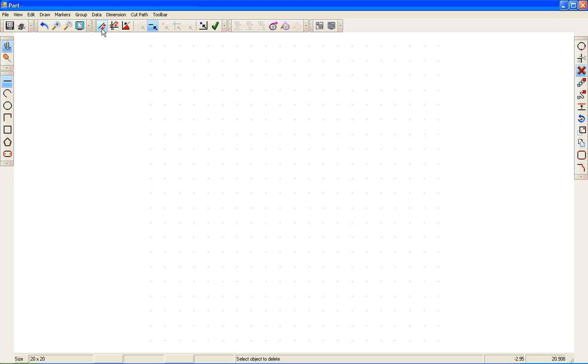Anytime you open up the program, there are a couple of things that you always need to check, and you always need to be aware of what is selected at all times, because depending on what's selected, it's going to make your program act very differently. I want you to start being aware of which input method, relative, absolute, or polar, is selected. I also want you to make sure which object usage icon is selected. Again, like I said yesterday, if you do not have the optional scribe tip for your plasma cutter, then you will always use the cut object.